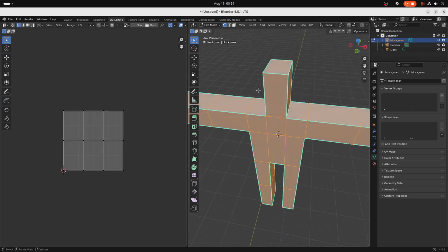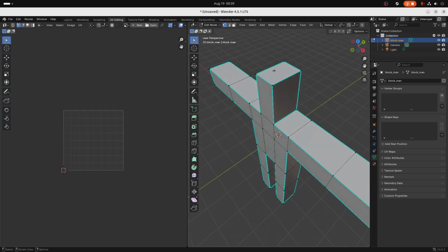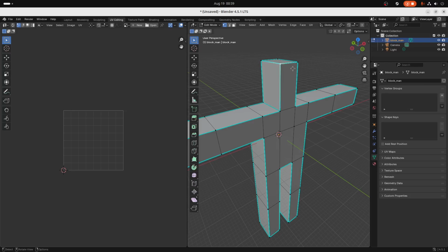Hang on. So let's see. Select all the points on the face. I think there's a way to actually select just the face in Blender, but I'm not all that much of an expert in Blender. Oh yeah, right next to the drop-down that has edit mode in it, you can select the edges or the faces. So I'm going to select face and then click on this face, and we see these points right here. At least I think that's it.